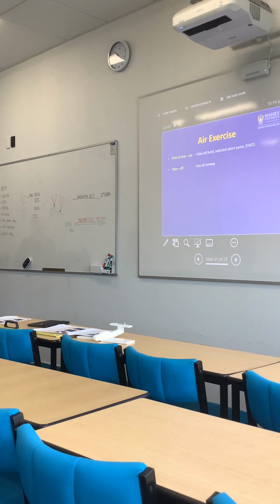As a tangent instructional technique, make sure you do that as instructors. Okay? We've had a CCAT almost fail their test. In fact, no, they did fail because they didn't backtrack. They just did, we always just go from Delta or Bravo, right? And we just say, oh, well, let's pretend the runway is at this dimension. No, you do it properly. You go back to the start of the runway, because otherwise you're giving the student permission to do the same. And they'll do that on a runway one day that isn't long enough, and they will run off the end of it.